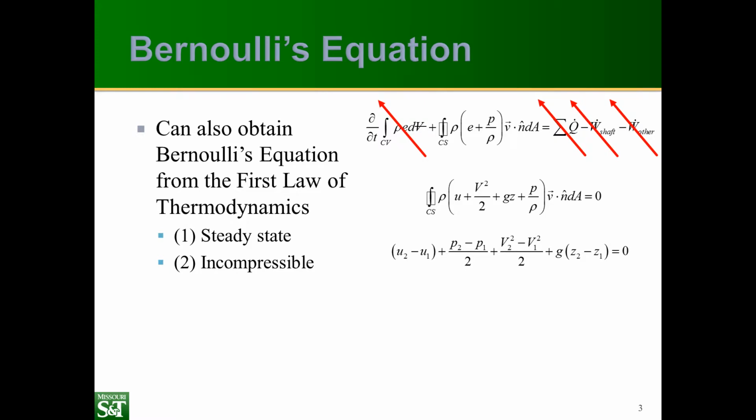This term represents the mechanical energy that's been converted into heat by friction, essentially by the viscosity. So in a real fluid, you lose energy from the mechanical energy of the fluid, and that gets converted into heat. So the fluid heats up. And that's this difference in internal energy.